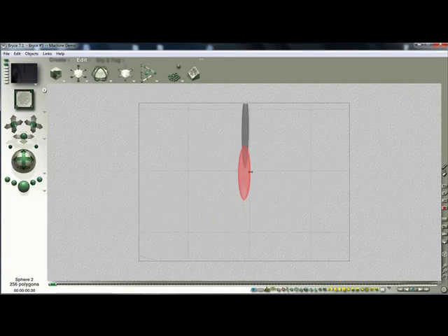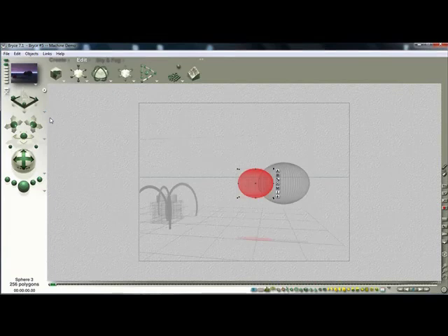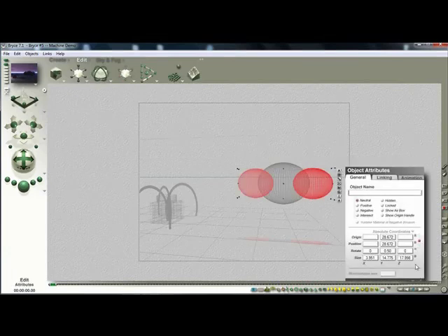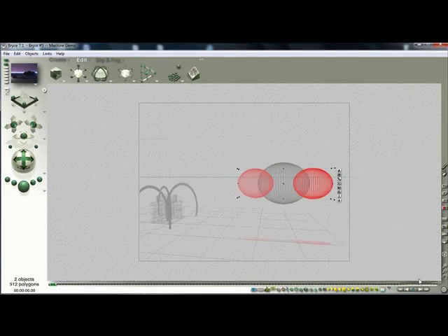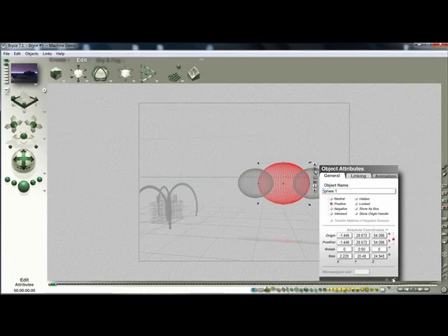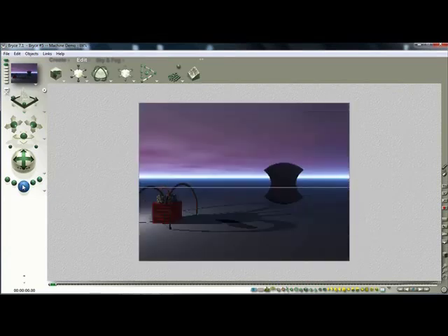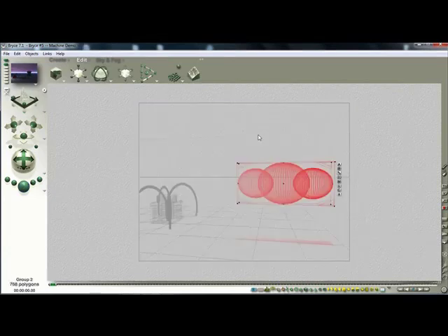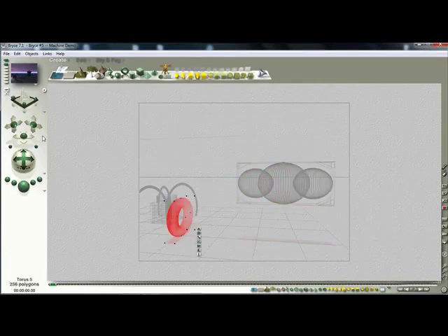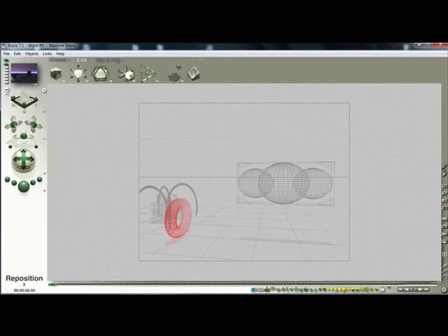So you want to make the object that's cutting into the other, of course, wider, so it gets all the edge. Okay, so I'm going to duplicate that and do the same thing on the other side. Now I'll select both of those objects. Those will become negative. They're going to cut into the other object. Select my middle object. That one has to be positive. Check. Now group them together, and you'll see that the two discs on the sides will cut into the other. That's what the negatives do. We'll give this a lead too, or two leads going into the ground.